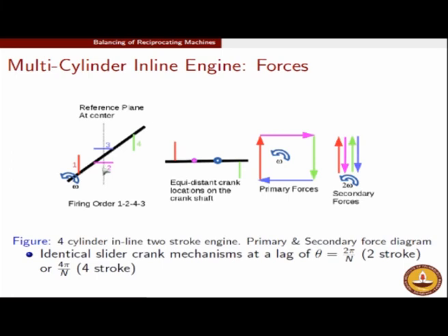In the secondary, since you have a 2 theta sitting in your trigonometric terms, the angle between 1 and 2 in the secondary will not be 90 degrees but double of that. So the angle will be 180 degrees. Similarly, the angle between 1 and 3 won't be 90 degrees, it will be 180 degrees. And lastly, the angle between 1 and 4 won't be 180 degrees but 360 degrees. So 1 and 4 will now get completely aligned, and 2 and 3 will now get completely aligned.